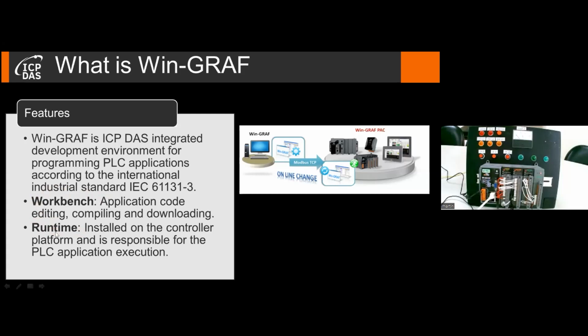The Workbench is a PLC programming software for programming our PLC series, and its development environment is for designing, programming, configuring, debugging, and maintaining machine applications. And the runtime is installed directly on our controller and is basically the operating system on which the compiled PLC application is running.